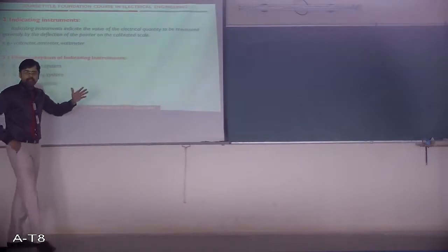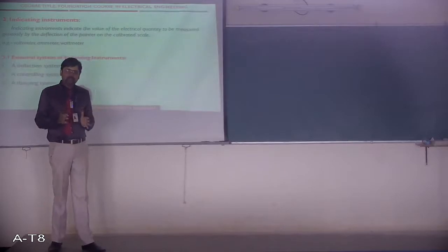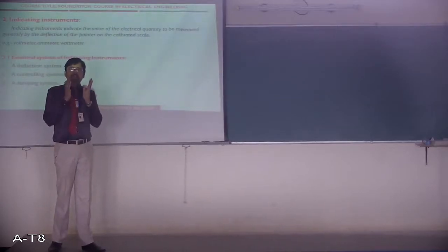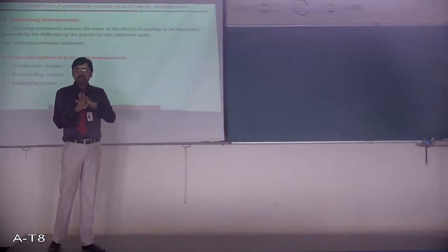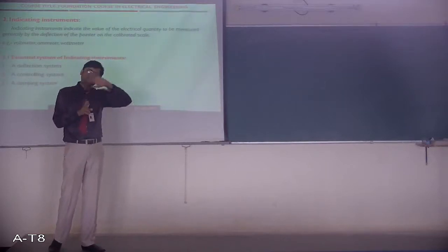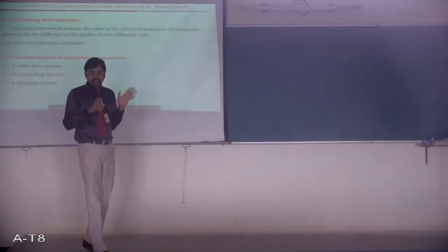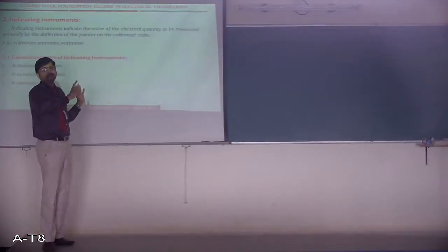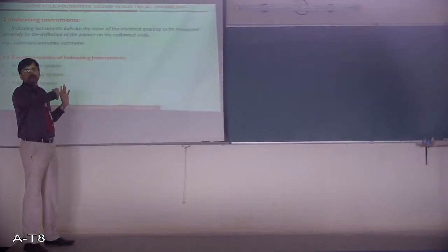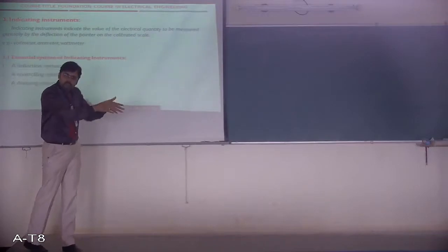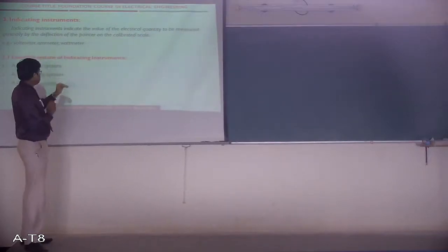What is deflecting torque or force? Deflecting torque or deflecting force is a force which is produced in order to move the pointer, and this force or torque is proportional to the quantity which we are interested in measuring. Okay, so deflecting torque is responsible for producing the force required for the pointer to move over the graduated scale, remember.